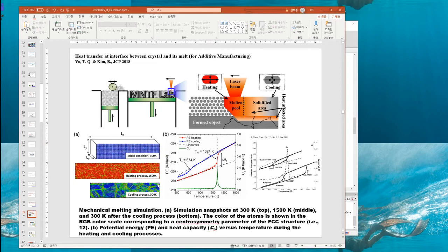So I did the melting and cooling modeling using MD, and I realized that MD can even capture the latent heat as well. When they melt from solid, they absorb energy, but the temperature doesn't rise. That gives a peak in the specific heat value.